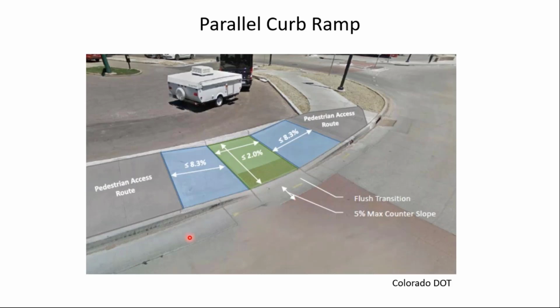And notice in this case, this is our PAR from back of curb to back of sidewalk. And actually, that's also the pedestrian circulation path. So in this case, the PAR and the pedestrian circulation path coincide. They are the same. I think in the other two examples where I pointed that out, the PAR was contained within the pedestrian circulation path, but here they coincide.